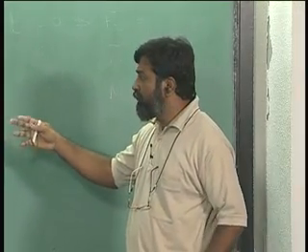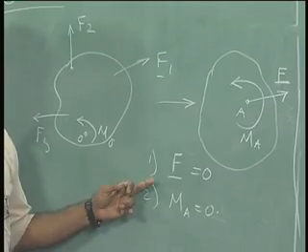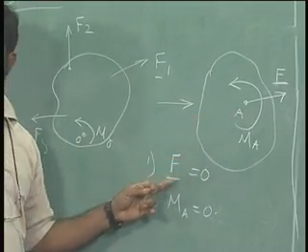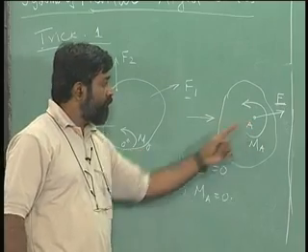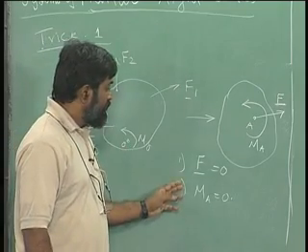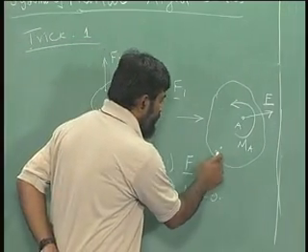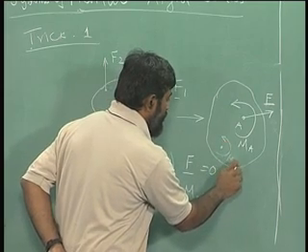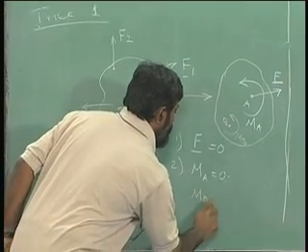All right. Now some of the points to remember here is, the resultant force is equal to 0, and the moment about this particular point A is equal to 0. Now the question arises, supposing I take some other point and I say, let us say I found out the resultant moment and that is MB. Can I add the other equation and say MB equal to 0?